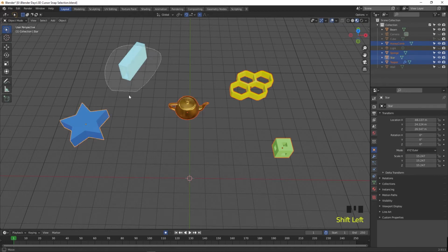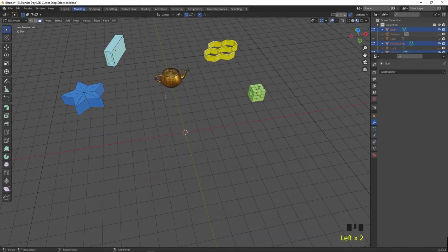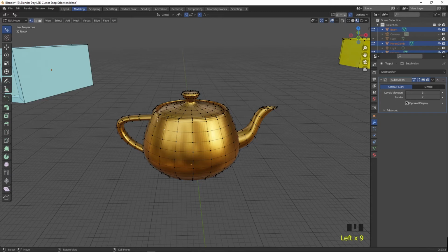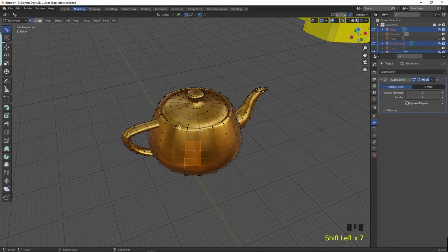This selection tools works same in the modeling mode. Select Menu, select All, to select all objects. Select Modeling tab. Selecting Polygon mode and select Tweak tool, and click on Teapot polygons to select it. Now activate Vertex mode and click on Vertex point on Teapot to select. Hold Shift and select Vertex to add Vertex to selection. With this tool, we can tweak the selection.